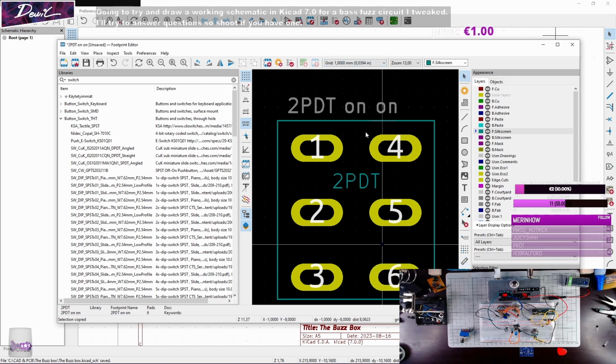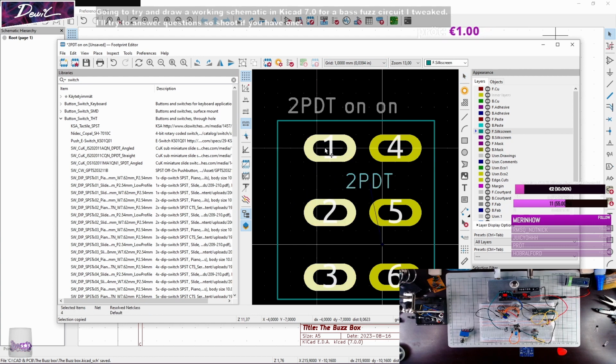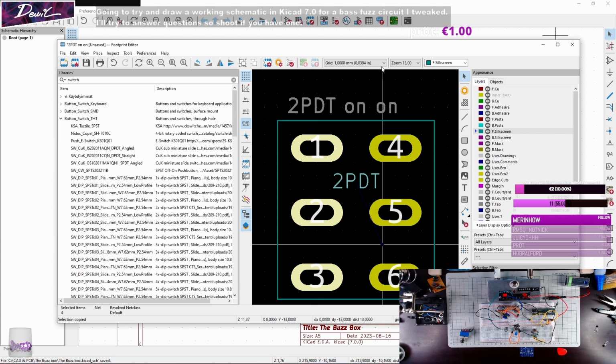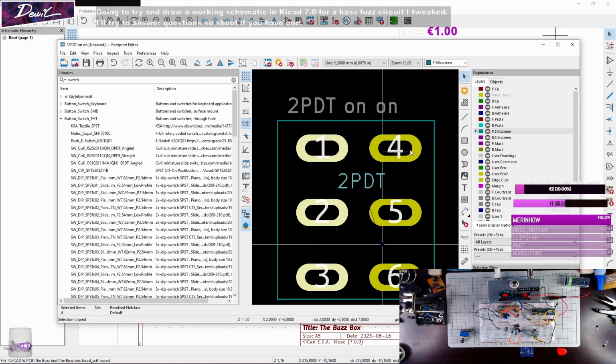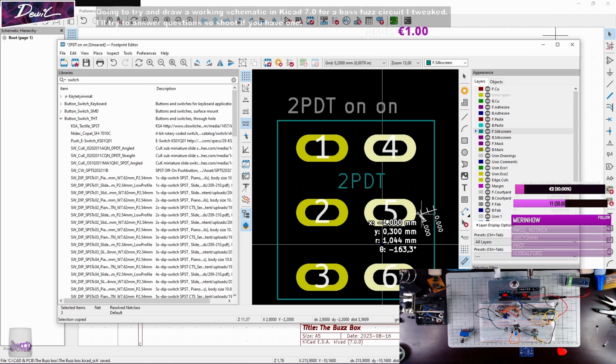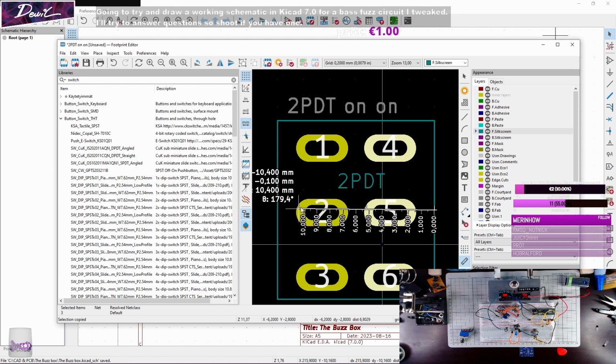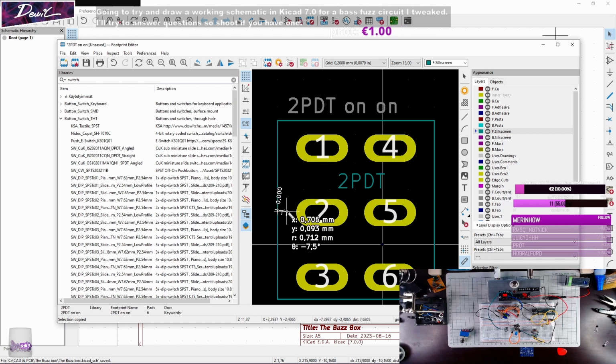So let's bring them both a bit closer. We're at mils again, so let's bring them a bit closer. All of these. Let's measure from the side. So that's like when you press Control, you can just freely measure, 1.350. ESC, and we get out of that mode.